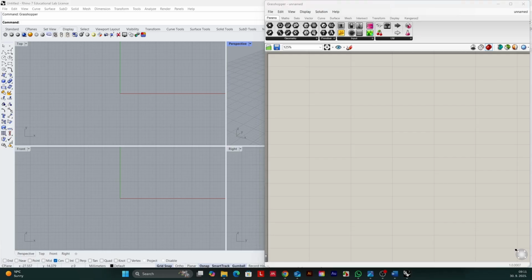And what is a body-centered cubic, or BCC, unit cell? This lattice has struts radiating from the center to the corners. It has in total 8 corner points plus one body center point at 0, 0, 0 or world origin. Struts means 8 straight lines in total connecting the body center point to each of the 8 corner points.